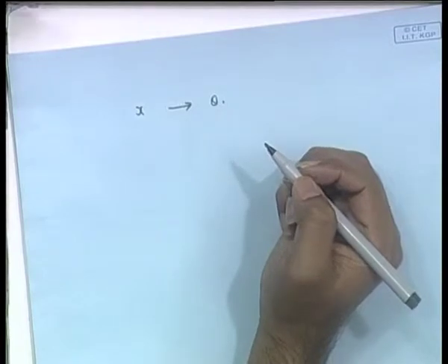Now, we are going to define the problem such that a trochoidal wave is defined like this. In a trochoidal wave, as the center of the circle moves a distance of lambda, which is the wavelength of the wave, the wavelength of the trochoidal wave being lambda, the particle rotates through an angle of 2 pi.